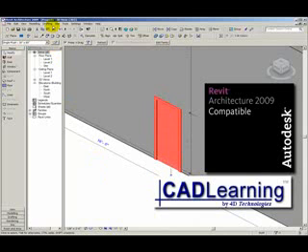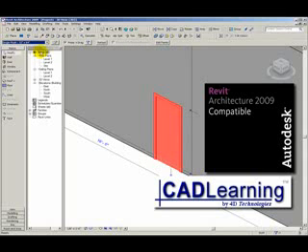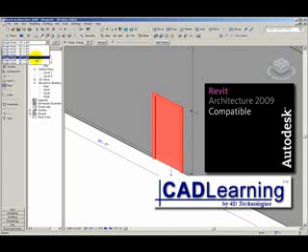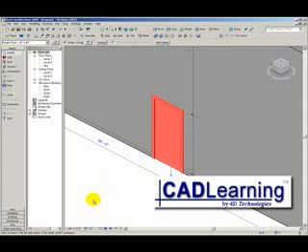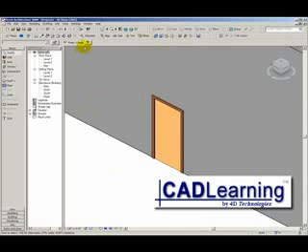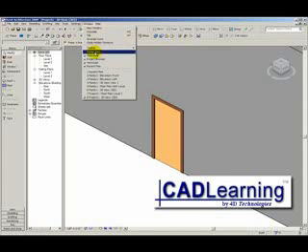When I select the door, the type selector shows me a list of various family types within the family, and simply by selecting from this list I can make changes in this particular object. I can change the properties of a family type and change many instances, more than one. Well, how does this work? Let's take a look at a family file.